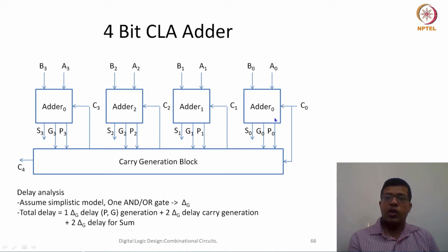In addition, we have introduced these additional AND and OR gates to get the generate and propagate signals, plus this carry generation block, which is also an additional area. So with this additional area, we are able to reduce the delay somewhat.